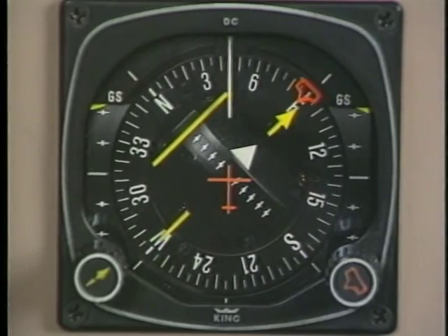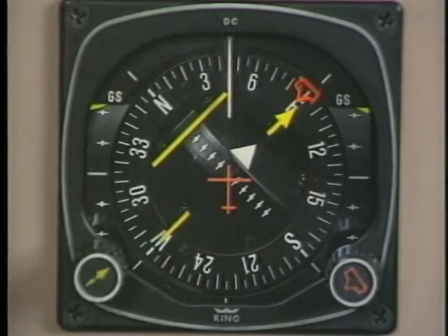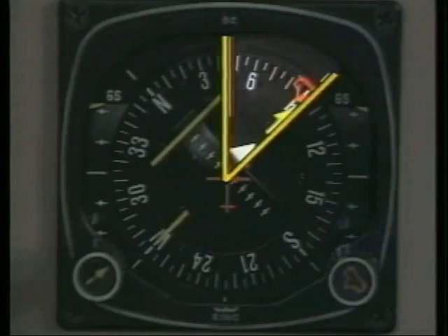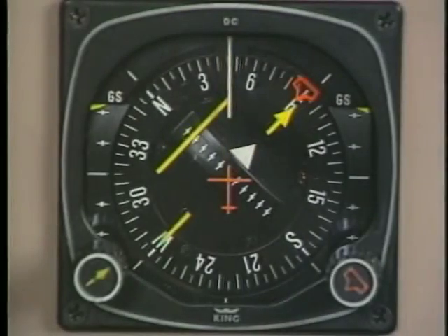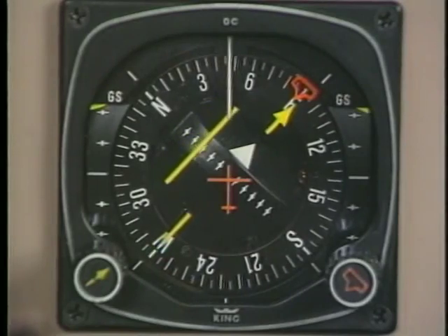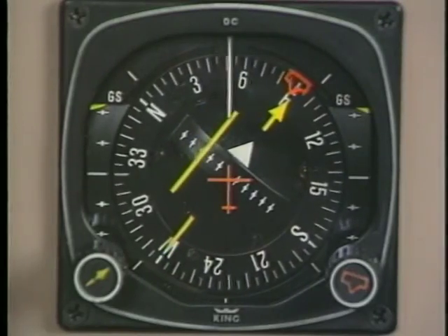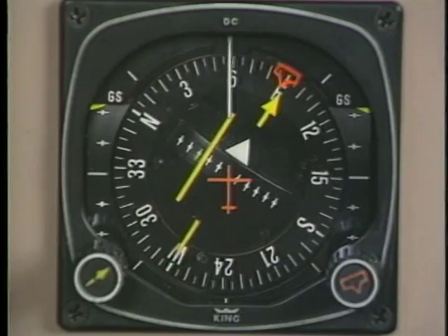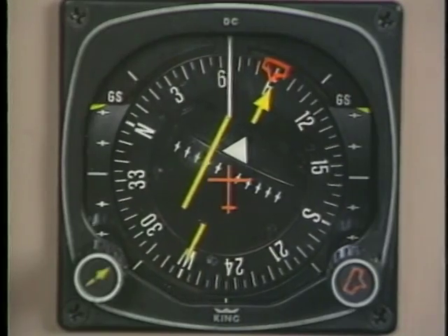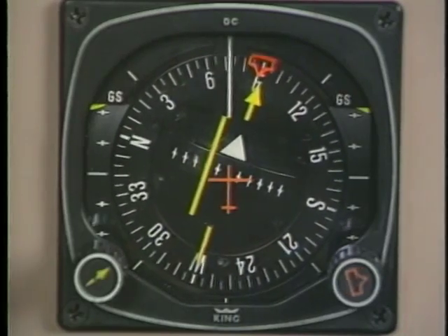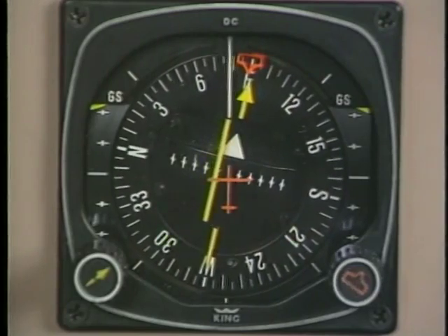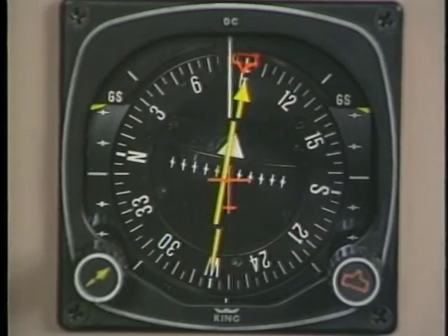After turning the airplane to 045 degrees, notice how the instrument shows your angle as well as your new heading. As you approach the radial, the needle will begin to move towards center to signify that you're nearing the course. You can gradually shallow the angle depending on your rate of closure to smoothly intercept the new course. You might have to adjust your heading slightly to compensate for the wind.